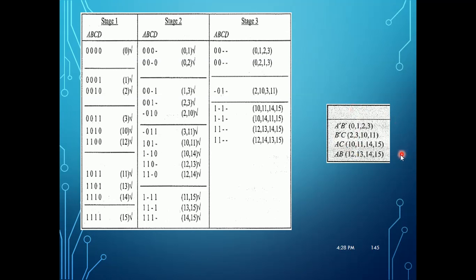different combinations now. So try to see that in stage 3 also, try to combine 0, 1, 2, 3 with the next term. Whether it is possible to combine, you just see. It's not possible. So try to see whether it can be combined with this term. That also you cannot do. So now the next stage will usually have 3 dashes. That thing you have to see. Whether it is possible to combine, go on trying with the different terms. It's not possible. So any combination is not possible here.